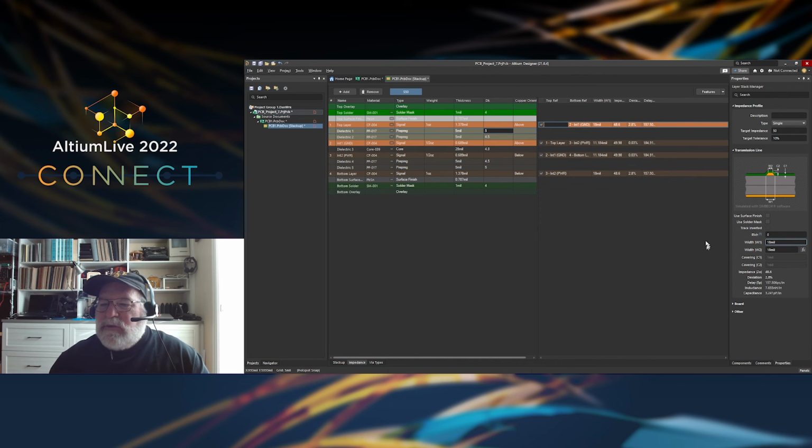But in addition, we can also evaluate some of the second order factors. So let's go back to 4.5 and 18 mil. So we got a 50 ohm line. Now let's turn on the solder mask. What's that going to do? Well, to first order, it shouldn't have any impact at all because it's so thin. But to second order, we're going to add a little bit of higher dielectric constant in this region up above.